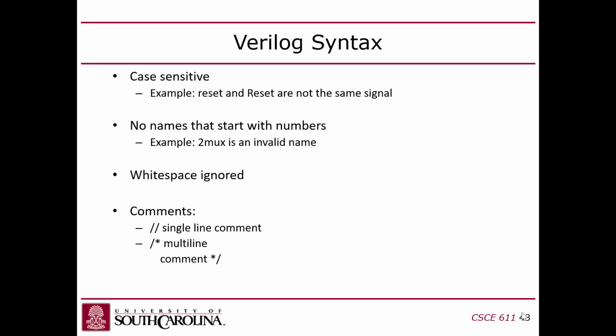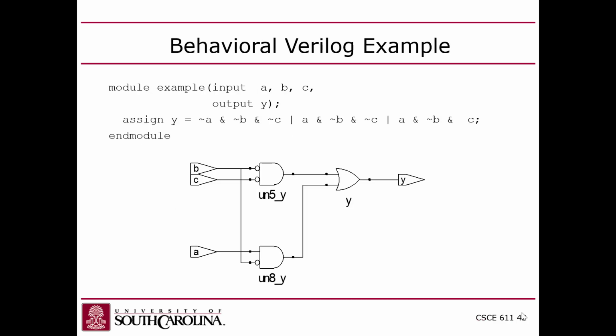This is significant because people have different styles for formatting their Verilog, especially when it comes to this part, because modules very often have lots of inputs and outputs. So notice what I did here is I've got input ABC, comma, output Y. So I put the inputs and the outputs on different lines. But maybe not most, a lot of people like to put each one of these on their own line. And furthermore, they like to line up the names, like tab things out, right?